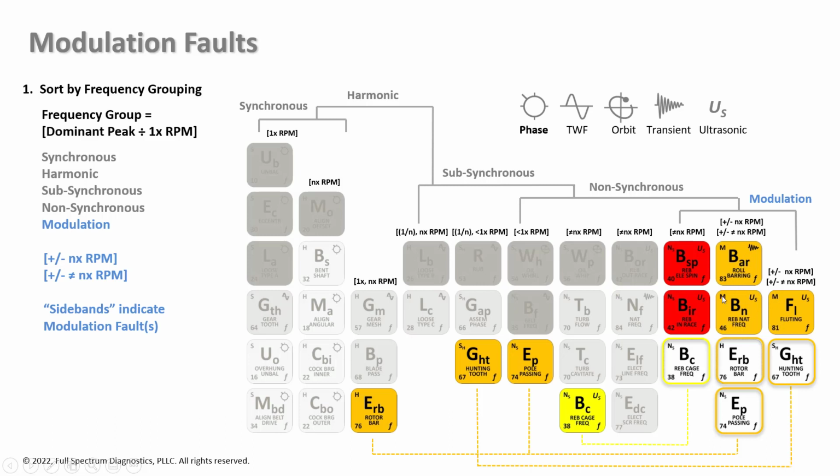And we can have natural frequencies that have 1 times RPM sidebands and fluting problems in the machine that have a little strange combination. They're a non-synchronous sideband, but they're the sideband at ball spin or inner race or outer race. So it's a special type.